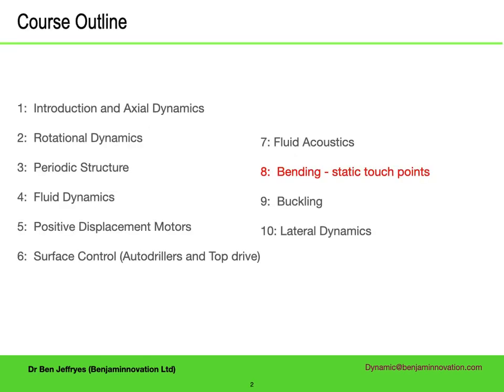This is the first of 3 sections on bending and on the lateral dynamics of drill strings sitting in boreholes. For this first talk of the 3, I'm going to be looking at the effect of periodic touch points on the propagation of quasi-static disturbances, so mathematically statics rather than dynamics. There are more degrees of freedom for lateral deflection than axial or rotational, which creates a much richer static range of behaviour laterally than axially or rotationally. Knowing how deflection propagates through structures is crucial to understanding how drilling direction can be steered.